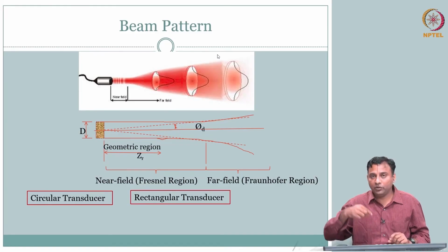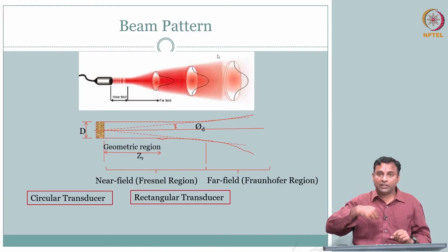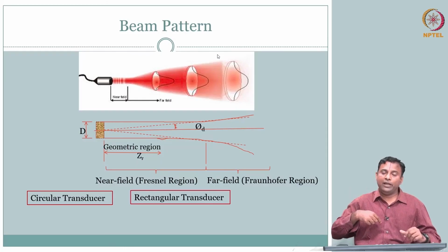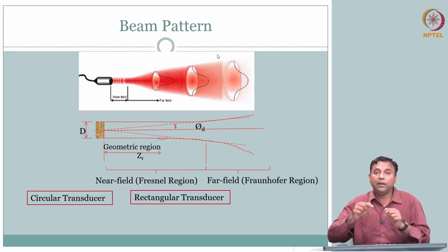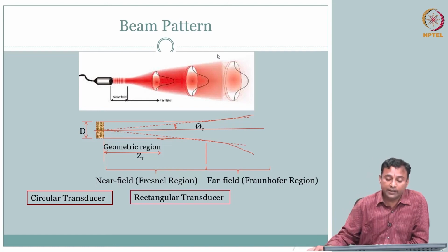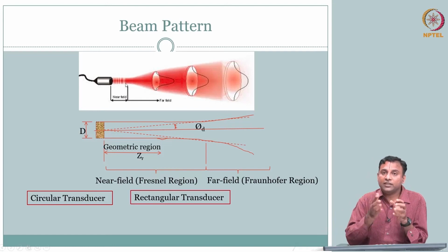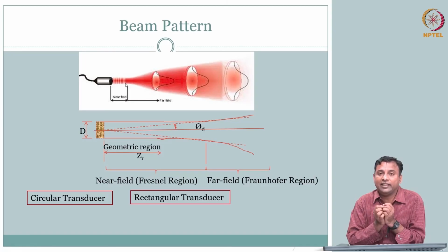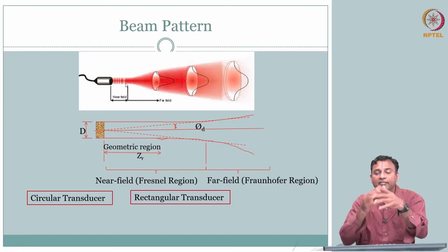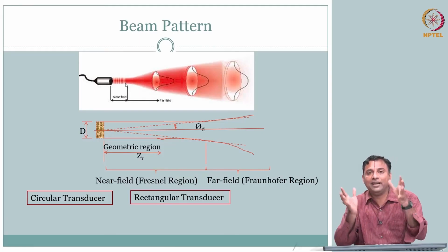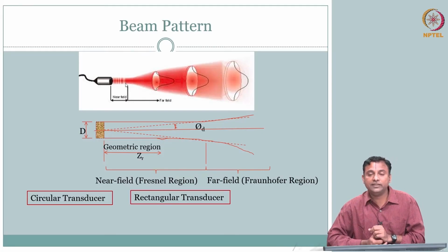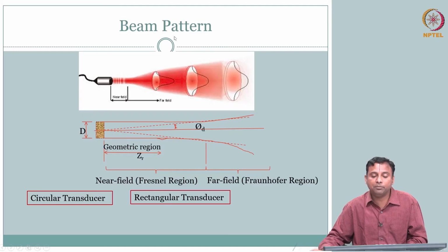I should be able to say, oh, it is situated 5 centimeters from skin and 4 millimeters to the left of the center. I should be able to say that, right? In that context, the transducer is generating the pressure wave, but it is generating this 3-dimensional wave, and it is also spreading. So now the question is, how do I describe this beam pattern? How do I capture this beam pattern?